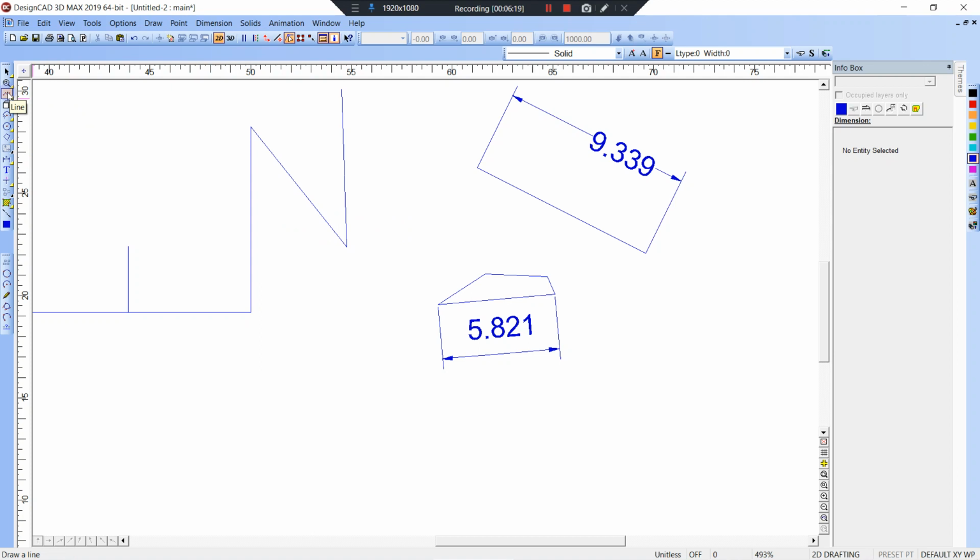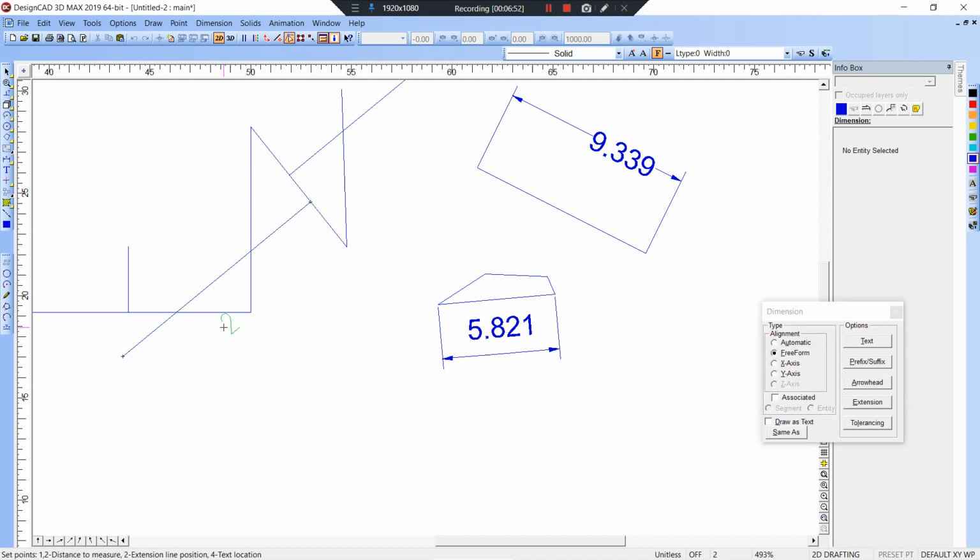So we're 6 minutes in. I haven't even gotten out of the first bar yet. But this is one that you're probably going to use the most, right? This is perpendicular from a line at a given distance. Let's hit that. So let's say 10 or 12, enter. And we're going to hit this line here, K, and it'll give me a 12 on that side. V, K. Oh, if we hit that again, I think it took me out. Hit that, K. Go that way. So that's your 12, your line 12 long.